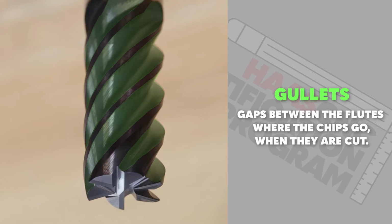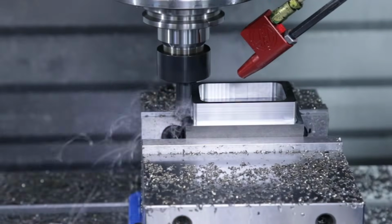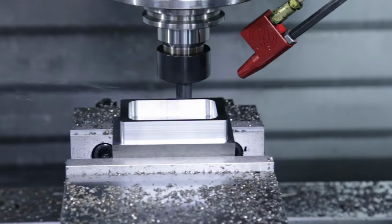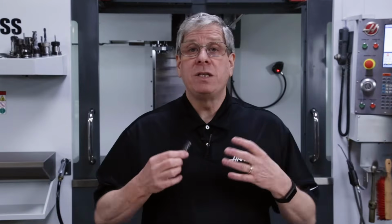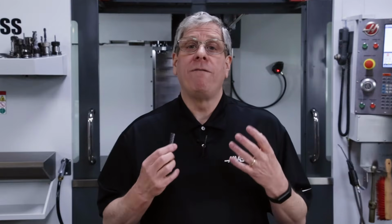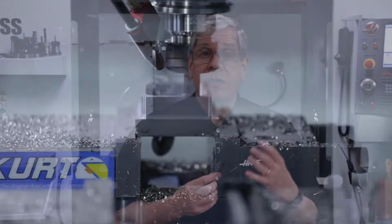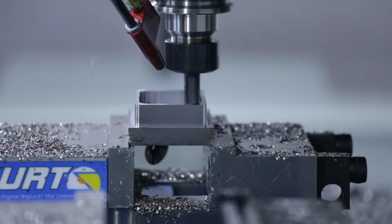Smaller gullets mean less room for the chips, so you cannot take an aggressive rough cut that creates big chips because there's nowhere for the chips to go. These multi-flute end mills are very good at finishing hardened steels where cutting large chips isn't usually done anyway, since the material is so difficult to cut.